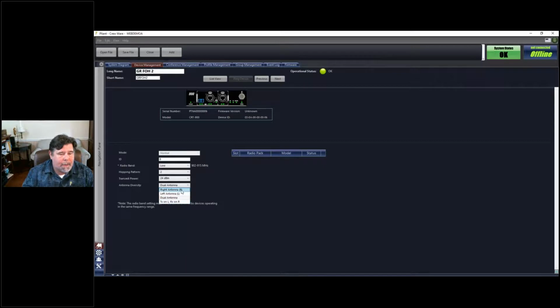And this is where you would adjust that, and also transmit on L and receive on R. We also have the ability to gain up and down our antennas. So if you want to have just coverage in a nice tight room, you can bring it down to 10 dBm and you're good to go. And that's about all I wanted to talk about there, Mr. Gonzalez.